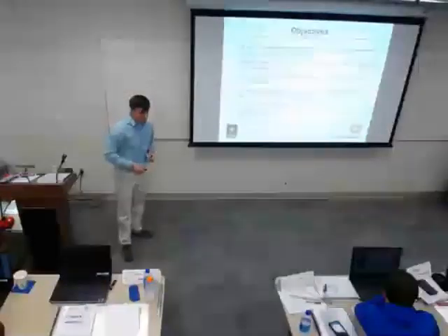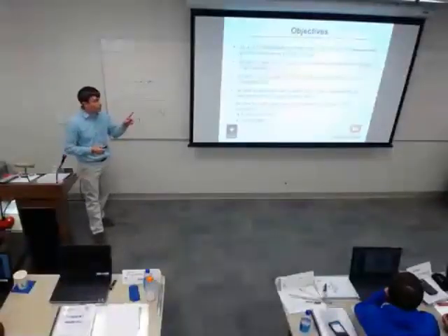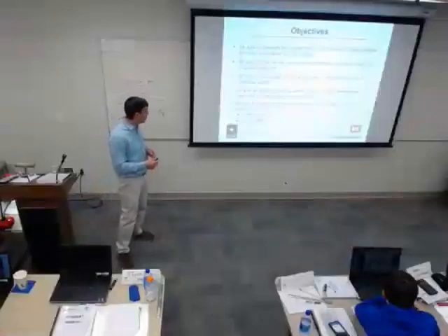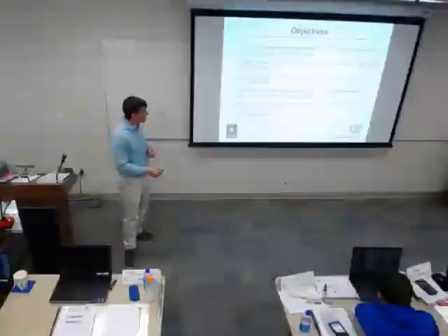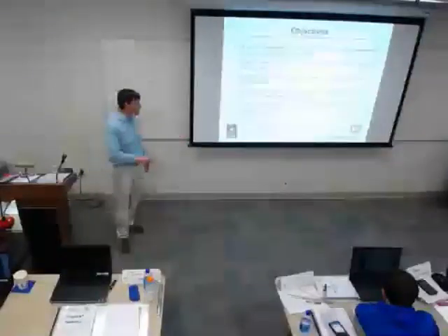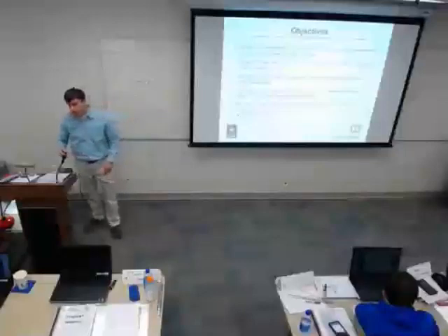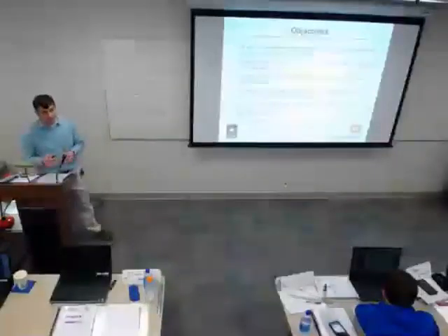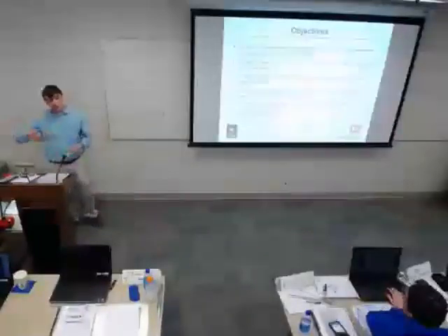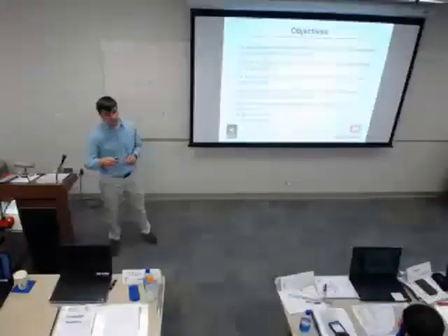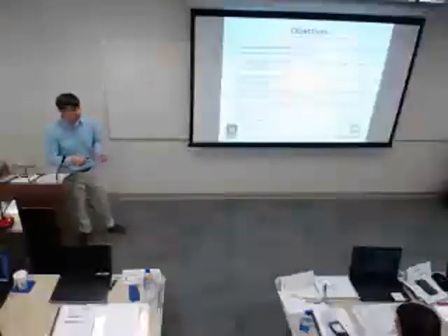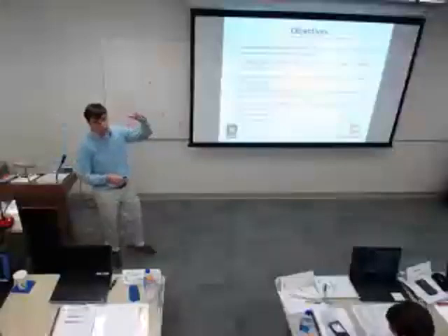We're going to go over fan laws, so more math, but these are important. These actually get used out in the field by your TAB technician if you've got to make an airflow change on a piece of equipment. We're going to talk about the various tools. There are a lot of examples over here of what tools you actually use to take some of these measurements. I'm also going to briefly go over the TAB procedures, how a TAB technician would go through and balance a building. They're abbreviated procedures. If you want the real procedures, go back to these books, which tell you exactly how to do it per their standard, and they are different per the standard. AABC has a little bit of a difference in the way they tell you how to balance an air side system and a water side system than the way NEBB does. But we'll go over them in general terms for thought process anyway.